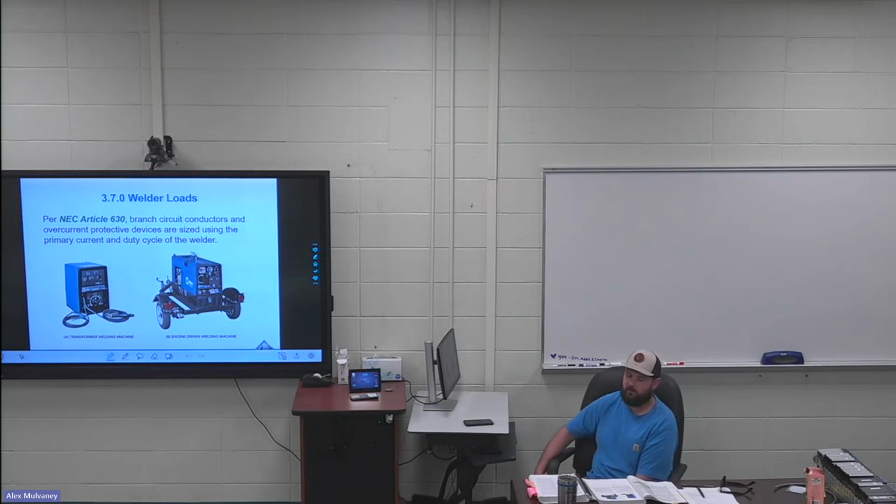For that highlight, key in on resistance welders and the 300%, shall not exceed 300%. And then I highlighted example 1 down at the bottom. That's where they're going to have a problem that you do with arc welders. Example 1 is pretty much exactly like the one in the quiz. Mine will have different numbers and stuff like that.